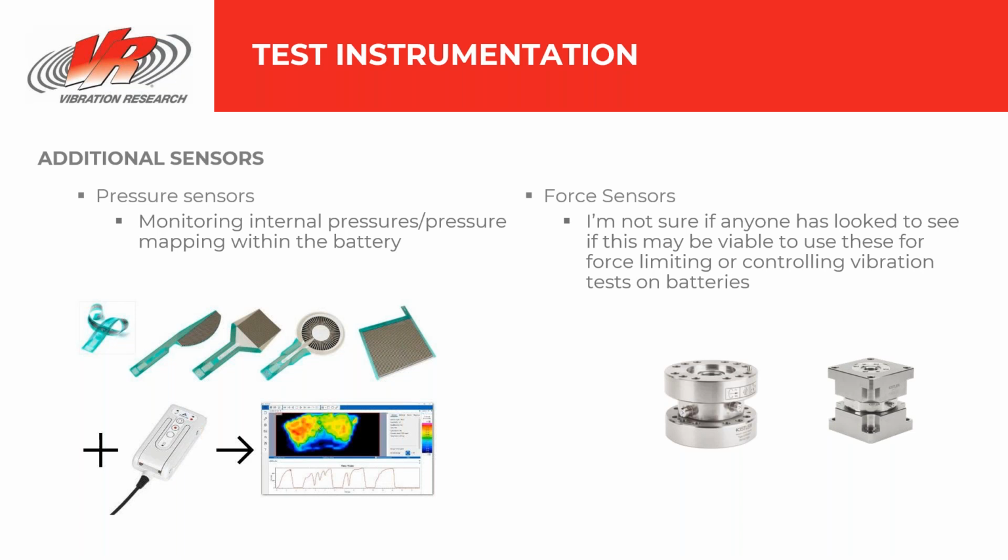So looking at force inputs, because some of the big battery packs, they react so much with their local surroundings, and the responses are going to be affected by the fixturing. So if your fixture's too stiff compared to the real life way in a stiffening up structure, you may get different responses. So quite often you can break things by putting in too much force.